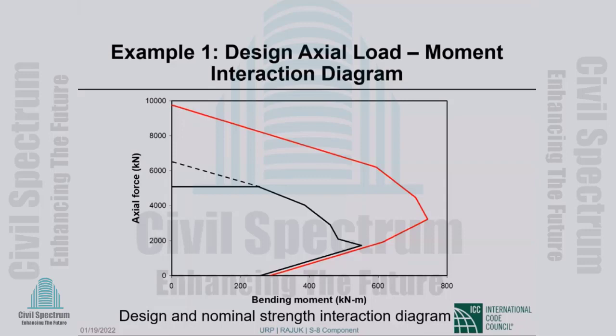You cannot do those things. If the design requires bars to be placed at the joint, bars must be placed at the joint. If bars cannot be placed, then you better change your design so that so many bars do not have to be placed in the joint. The other measures that are taken, pea gravel and superplasticizer and all of that, cost a lot of money, and they should not be required if the joint is properly designed.